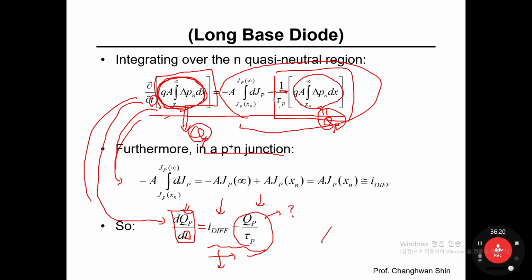Then you will see a simple infinitesimal volume, with input current and output current at x plus dx, and some magic can happen within this infinitesimal volume. The magic was recombination and generation. In terms of equation format, it is quite similar to the continuity equation. The very first term on the right hand side would be the current flow.